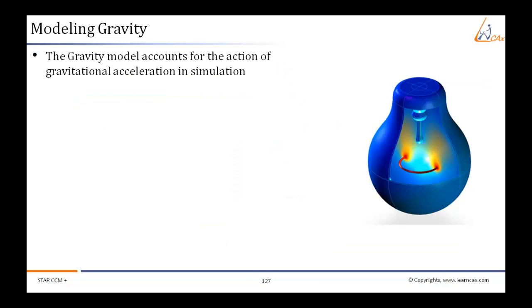When gravitational acceleration and force are going to be the predominant force for fluid flow, we need to include gravity effects in the simulation. For this, there is the gravity model. The gravity model accounts for the action of gravitational acceleration in STAR-CCM+ simulations.